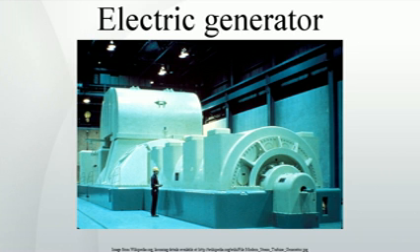MHD generator. A magneto-hydrodynamic generator directly extracts electric power from moving hot gases through a magnetic field, without the use of rotating electromagnetic machinery. MHD generators were originally developed because the output of a plasma MHD generator is a flame, well able to heat the boilers of a steam power plant. The first practical design was the AVCO MK25, developed in 1965.